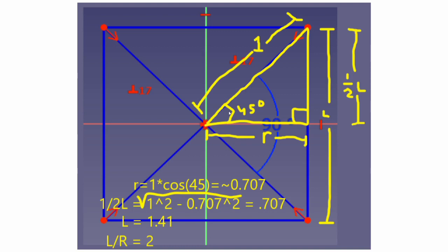So let's just arbitrarily say that we're building a bowl, and we intend for the distance from the center to the point to be 1. And I'll do that a lot throughout this analysis, where I'll just arbitrarily set the length of something to 1, and that's fine. So now I have a triangle where I know the length of the hypotenuse, I know the length of one of these angles, I know it's 45 degrees, because remember 360 divided by 4 gives us 90 for this angle here, so this has to be 45 degrees. And now I can use SOHCAHTOA, and I can figure out the length of R. R is the hypotenuse, 1 times the cosine of 45, and that works out to about 0.70.